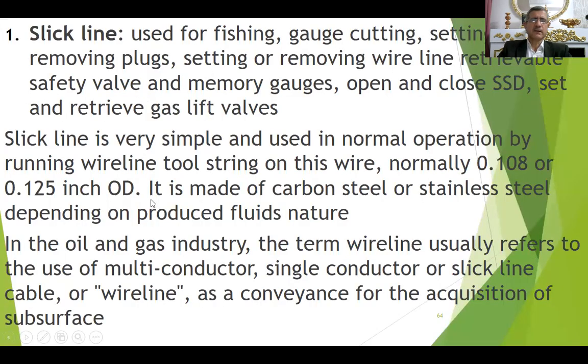This is the slick line. It is stainless steel. We can do most of our operations, such as gauge cutter, setting and pulling plugs. We can also set and pull the subsurface safety valve, set and pull the memory gauge, open and close SSD, and set and retrieve gas lift valves. Slick line is very simple. It has two ODs, 0.108 and 0.125 inch.